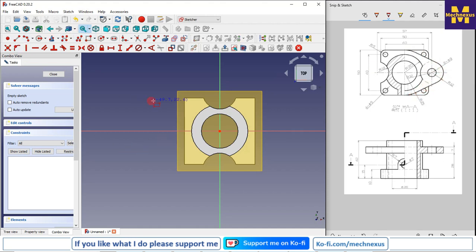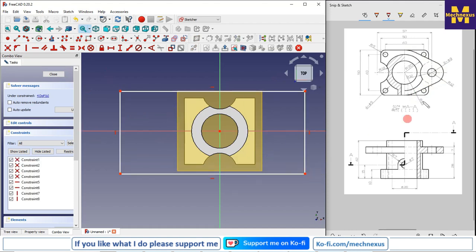So for this I will simply create a rectangle. Now we will find the length and width of this rectangle. So you can see that here center to center distance is 57 and this is R12, and this R is on both sides because this is the aligned section.